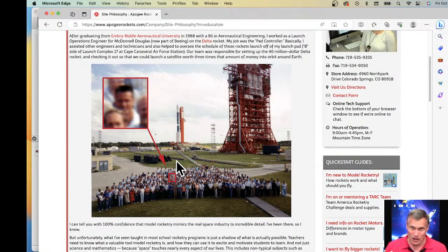nitrogen, and because we were launching in Florida, there's so much humidity in the air, and humidity and metals, it causes corrosion. So you don't want your rocket corroding while it's sitting on the pad, so they pump in nitrogen and it flows throughout the rocket, and it forces out any water. So we'd have to turn all that stuff off. And it took about an hour to turn all that off, and so we're standing on this burnt launch pad.